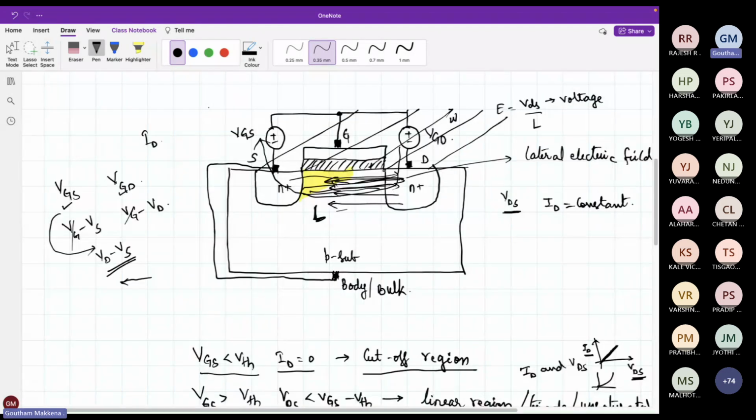See, this is an N-type semiconductor. This is a P-type semiconductor, right? Now, can I say that there is a diode forming between these two? Yes, we can say. This P substrate is connected to ground, and this N type is connected to a positive voltage. When I'm talking about VDS, drain is the positive voltage. This is connected to some VD, a positive voltage. So what bias will this be? Reverse. So this is in reverse bias.